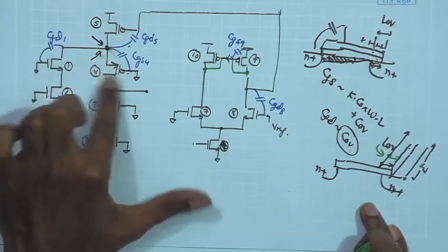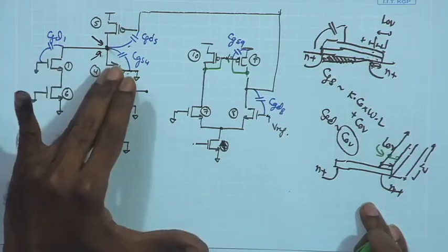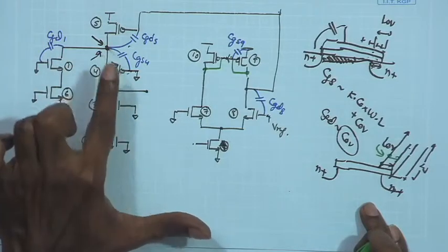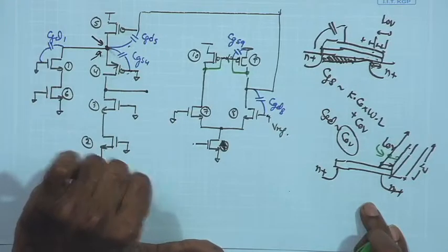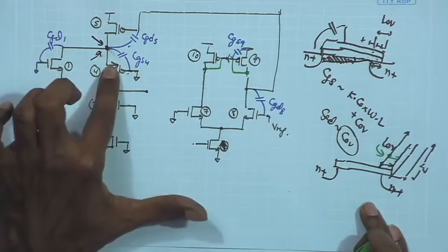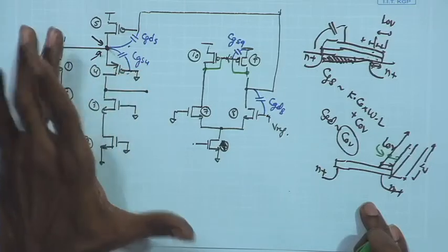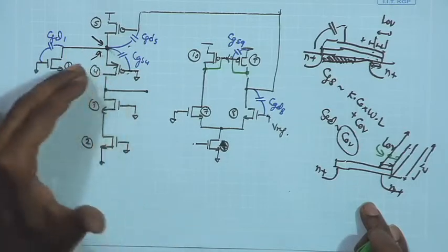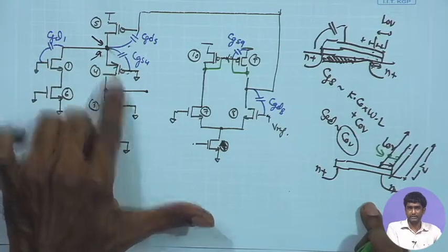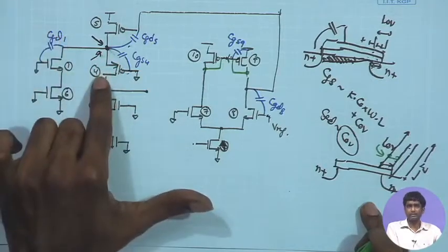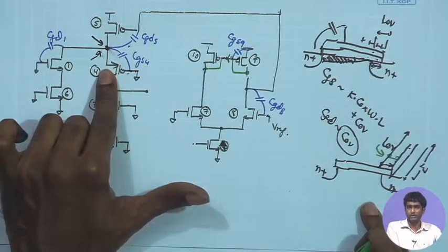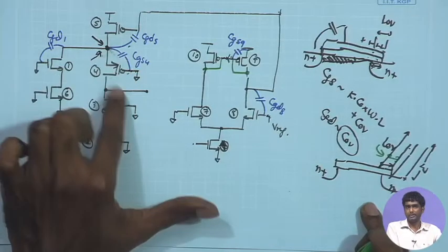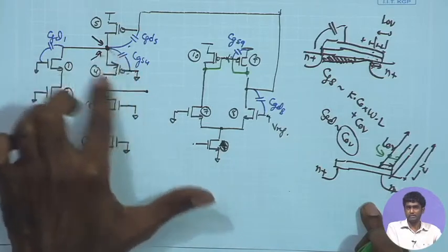Likewise, for this device, the W by L may not matter too much. The Cascode device, we will see very shortly, also does not play a very important role in determining the noise of the Cascode configuration. Therefore, for the Cascode device, once again the GM does not play a very important role, and we can afford to sacrifice the GM of this device significantly by reducing the W of this device significantly. So, if you want good gain, L can still be kept large, say 2 micrometer, whereas W can be reduced so that the CGS4 is within limit, because the gain does not depend upon GM of this device, it just depends upon the RO of this device.